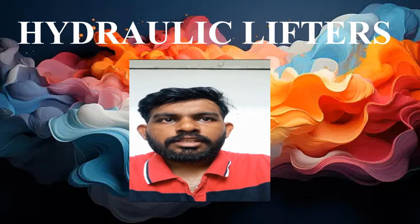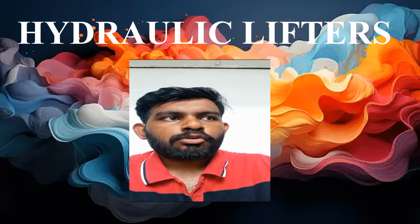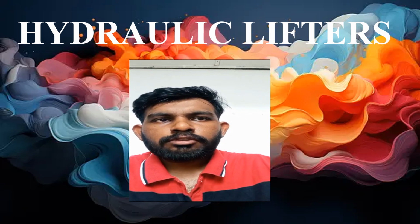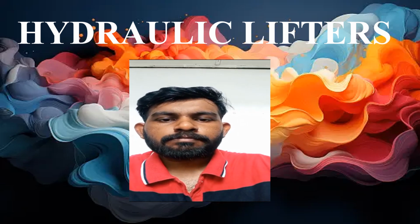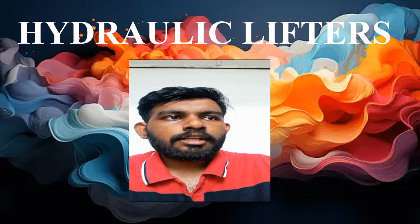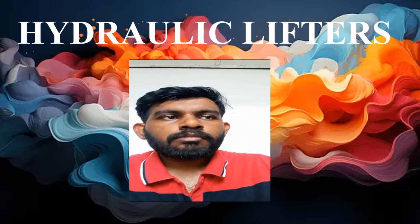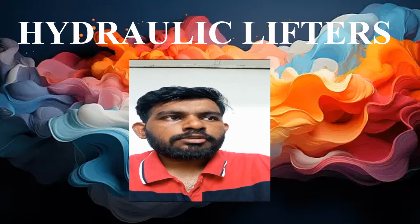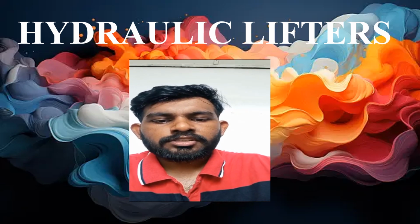When the engine is running, the camshaft rotates and pushes against the plunger in the hydraulic valve lifter. This causes the plunger to move upward and compress the spring. As the spring compresses, oil is forced out of the lifter through the check valve and into the engine oil gallery. This creates a hydraulic cushion that effectively adjusts the valve clearance and ensures proper valve operation.